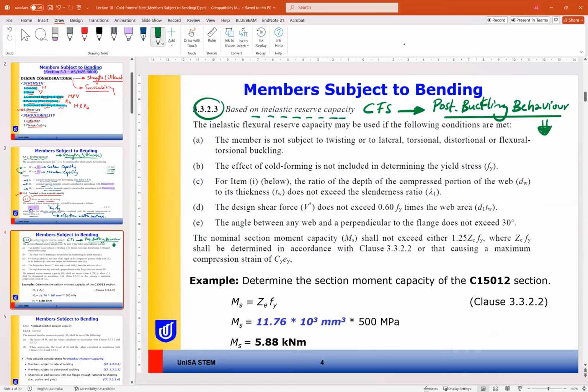So for cold formed steel sections, we have what the standard calls inelastic reserve capacity. The section, after the post-buckling behavior, can generate more strength after buckling.